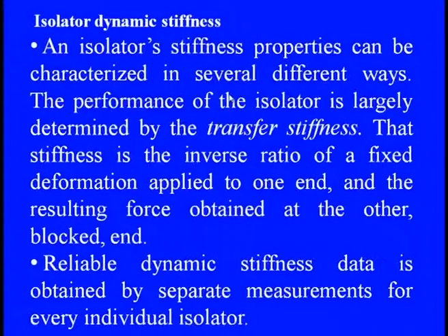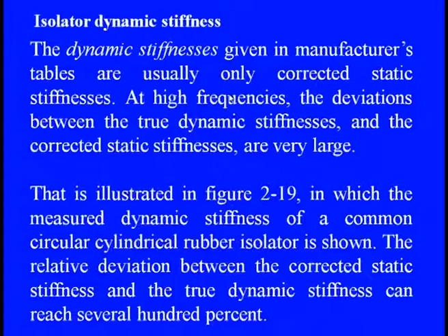And then reliable dynamic stiffness data should be obtained separately for every individual isolator for appropriate design of the isolator under dynamic stiffnesses. Because the manufacturer is just providing the data, it is always there, but it is only connected to the static stiffness.